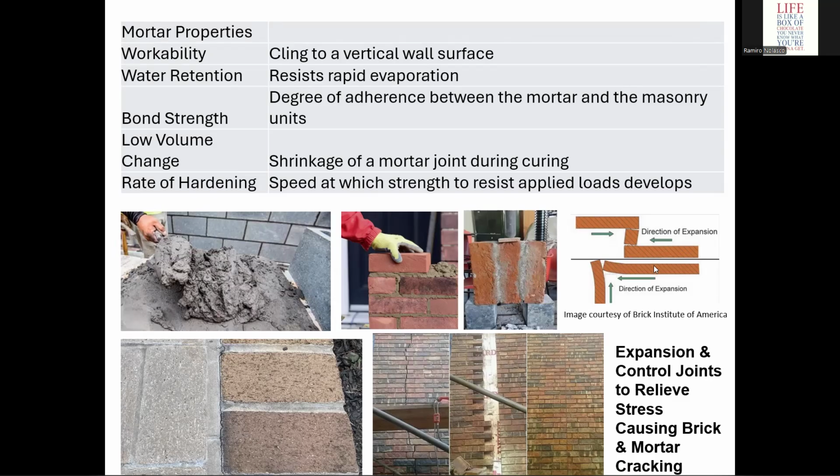See, even with brick, right? It will expand. These are the direction of expansion, causing some cracks, aside from maybe the earth moving. Okay, so that's why you might need to add expansion and control joints to relieve the stress, causing the brick and the mortar to crack.